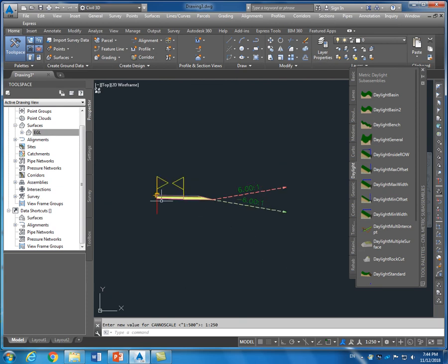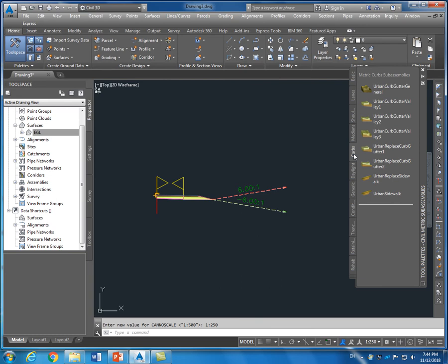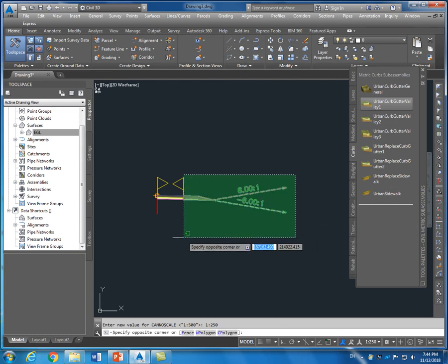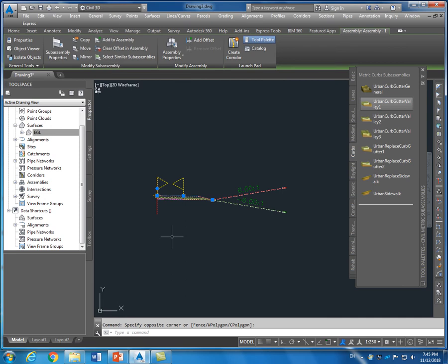That was a basic 2-lane, both direction rural road. For an urban road, you may need the curbs, sidewalks, and things like that. These urban sidewalks are also possible to design here, but for the sake of simplicity, let's go with it. Now you have to select this daylight, shoulder and lane.